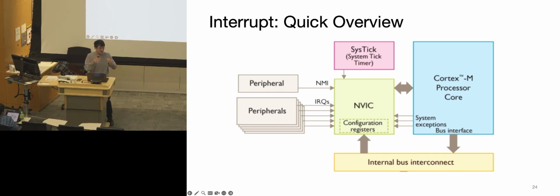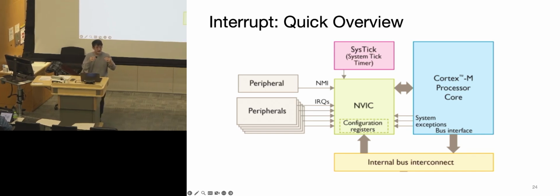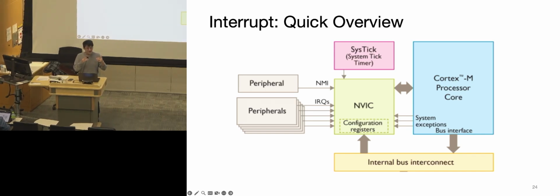Remember, each of those types of interrupts is hardwired, so they have a designated signal, one number assigned to it. We'll show you in more detail later, but it's very fast, and the processor gets that information immediately, and it knows where it comes from because they are hardwired.